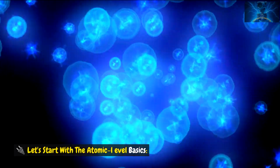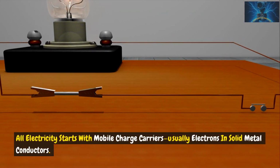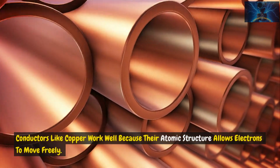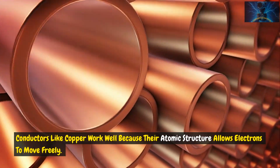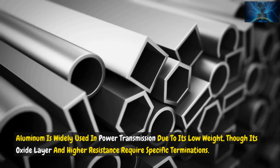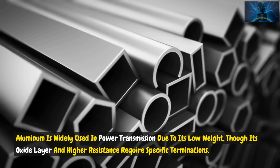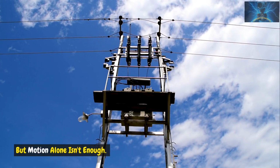Let's start with the atomic level basics. All electricity starts with mobile charge carriers, usually electrons in solid metal conductors. Conductors like copper work well because their atomic structure allows electrons to move freely. Silver has even lower resistance but is costly. Aluminum is widely used in power transmission due to its low weight, though its oxide layer and higher resistance require specific terminations. But motion alone isn't enough.